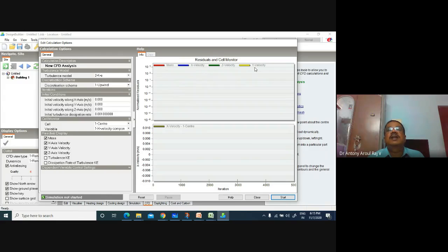But velocity is a vector, so it will have a 3-dimensional form. So what is the component of velocity? That you can have in the plot. So you will be getting 2 plots: one is the velocity plot and another is the pressure plot. In specialized CFD solvers, you can get individually what is x velocity, y velocity, and z velocity. So you can get it separately also. That means if you are solving 4 equations, you will get 4 plots. Regarding this also, we will be studying in detail.